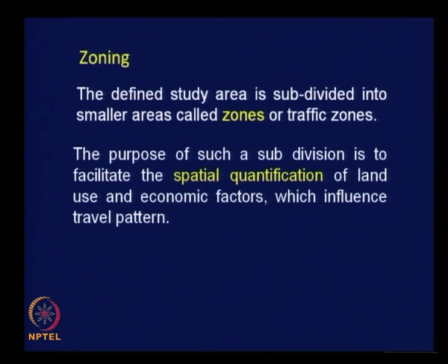The purpose of such a subdivision is to facilitate the spatial quantification of land use and economic factors. What do you understand by spatial quantification of land use and economic factors? You must cordon off some space, some area, and then study the socio-economic characteristics of that area, so that that is taken as an attractive force or trip producing force.